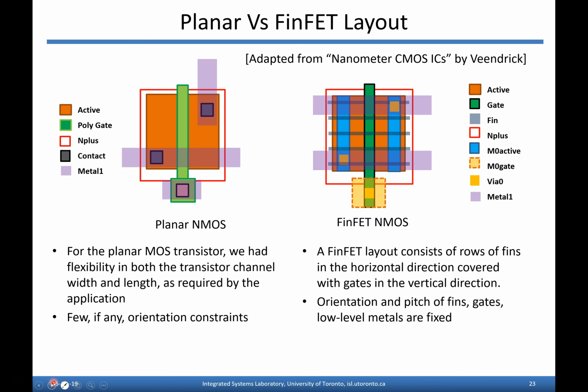So now a few slides to talk about the different layout styles that show up with FinFETs, because that's again important in determining performance, because the parasitics are so significant. So this kind of picture is probably familiar to you. It may not be the best transistor layout you could ever imagine, but you understand what's going on here. Green gate is running vertically, and you've got a drain and source region in orange and contacts to that, bringing it up to metal 1 in purple here.